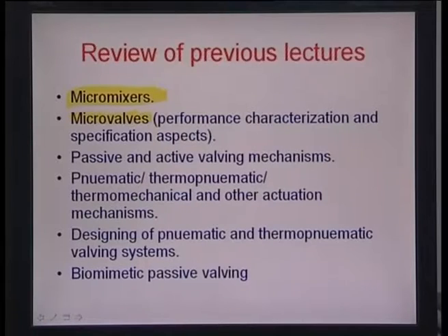We then detailed micro valves, essentially tried to study some basics about their actuation mechanisms, their performance characterization and also specifications. So, some of the aspects like valve capacity, the leakage ratio, the power requirements, and other aspects like material selection, biocompatibility, etc., were discussed for designing micro valves or micro valving systems.